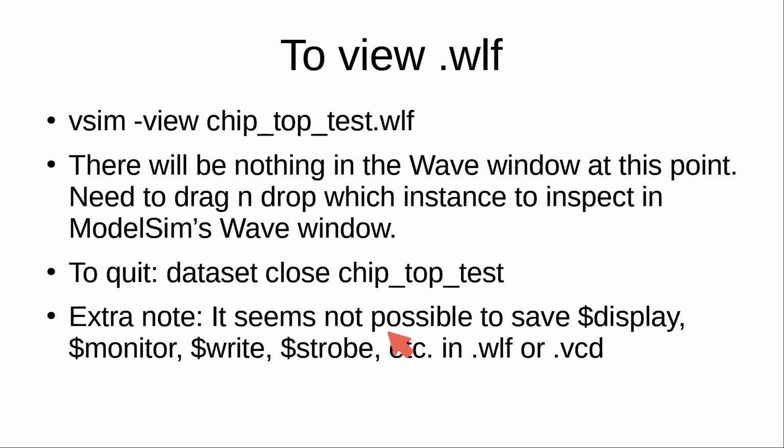And it seems like it is not possible to save the output from the display, monitor, write, strobe, etc. in the wavelog format or VCD, because this wavelog format or VCD are saving only the output of the wave window. So I don't think there's a way to save the transcript window output.